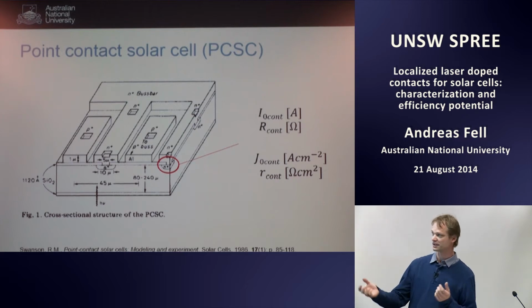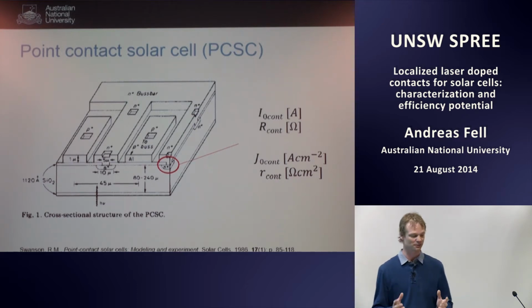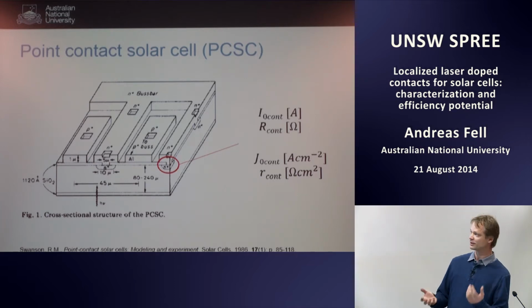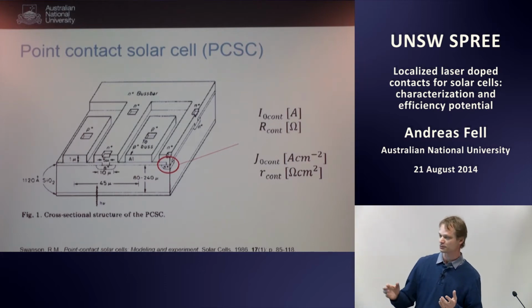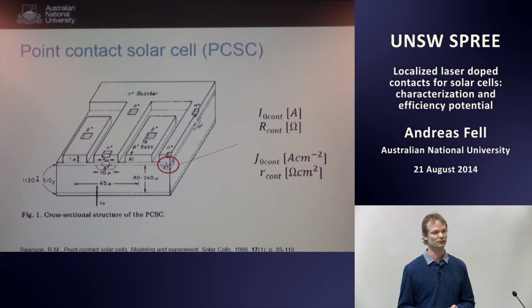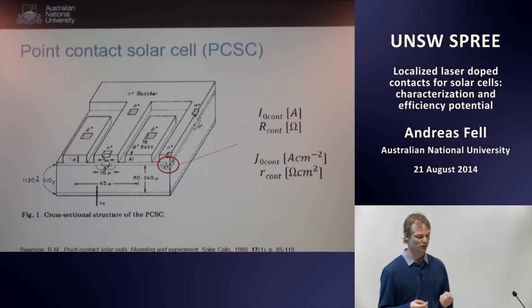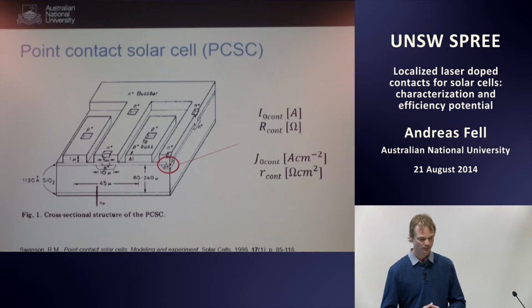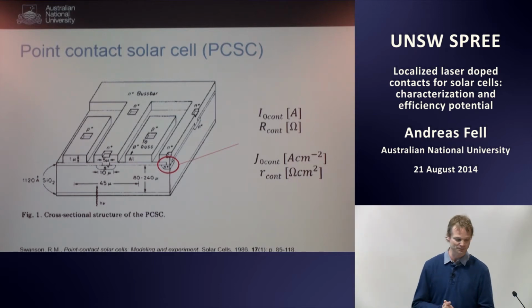So you might actually have very different recombination properties within that small contact. But it turns out it doesn't really matter. However you distribute your total recombination within that contact, the only decisive thing for the cell performance is the total recombination current. This is true because the contact is small, so any lateral variation effectively smears out in its impact on the device. We've proven that by simulations, but you can also do some analytical estimations and see that it's valid.